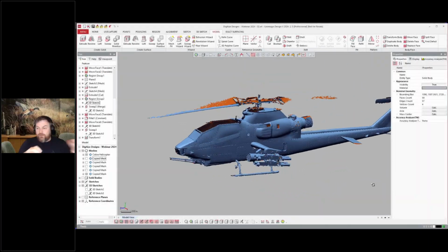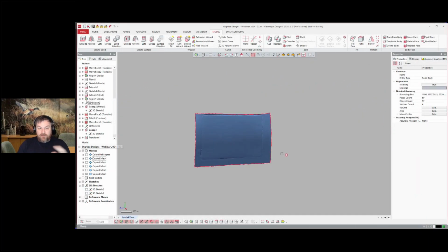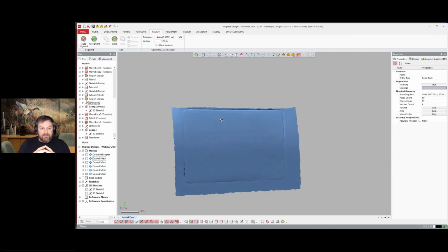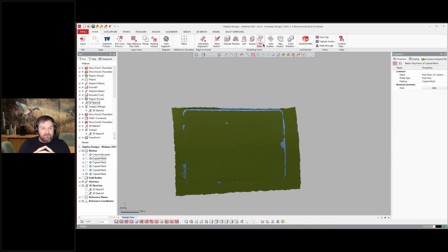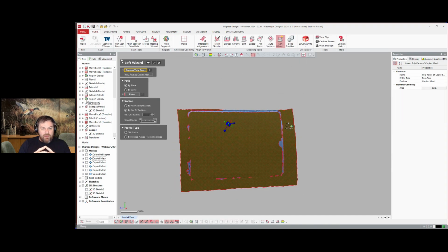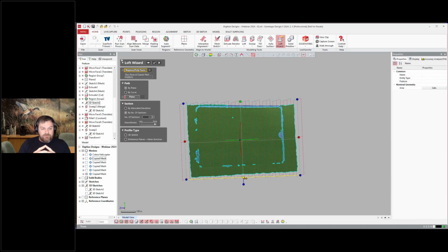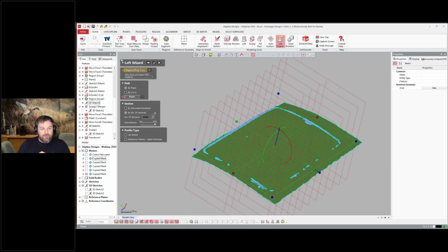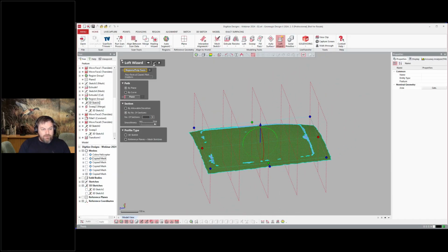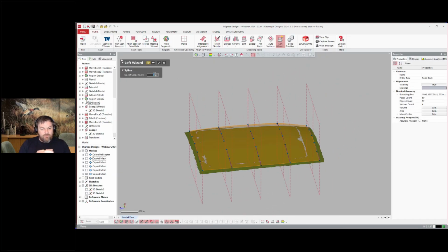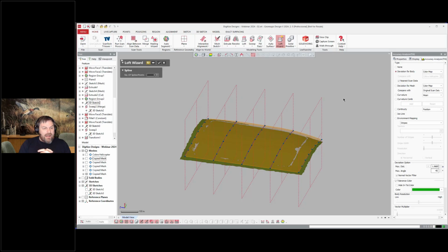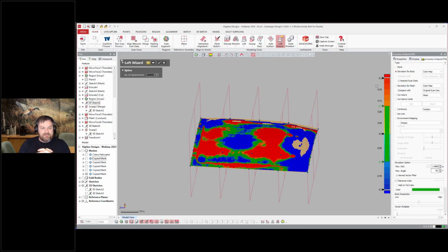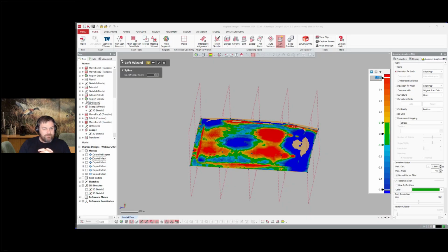So some of the other tools that are in here, we're basically doing a collection of lots of different things that would help within an application like this, where you have maintenance on these military vehicles here. If I needed to recreate this door, whether I'm modeling the entire part or just this component here, you see I can create a region on that door panel, and I can adjust the tolerances and do a 3D compare and just see how closely I'm fitting to that mesh.